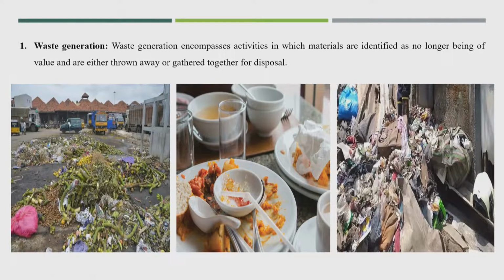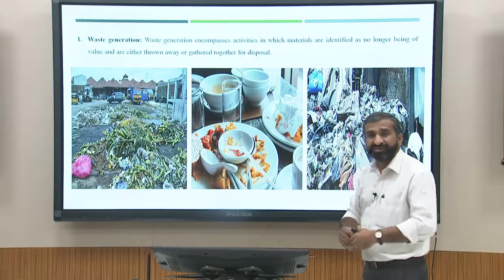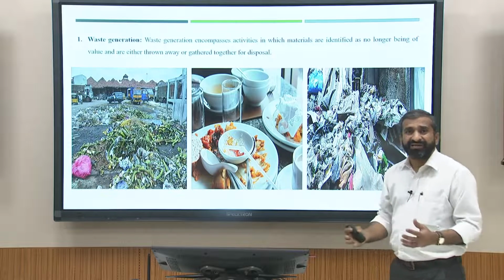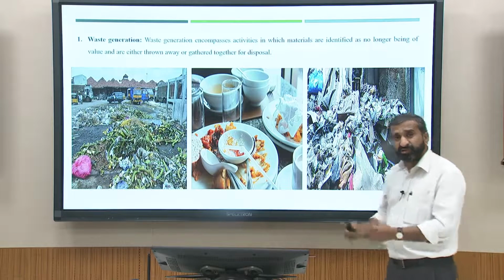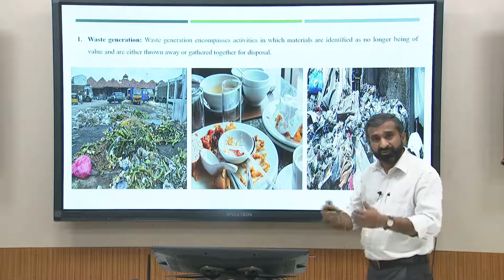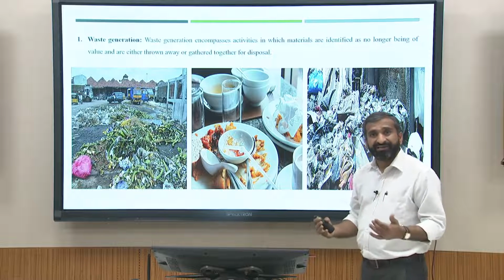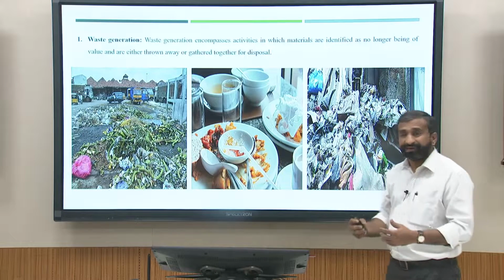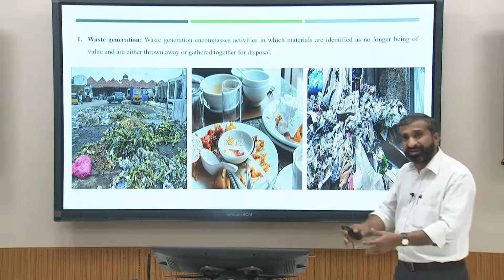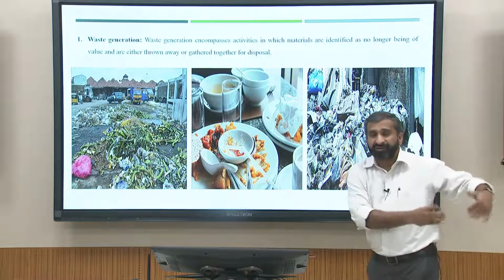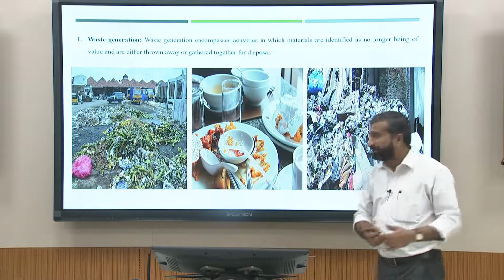Obviously, the collection system will be different for such waste, because it is normally biodegradable. Once it is stored for a longer period, it will produce odor and a lot of leachate, so a lot of issues will be created. So we should have a proper collection system and provide it for the biological treatment process.